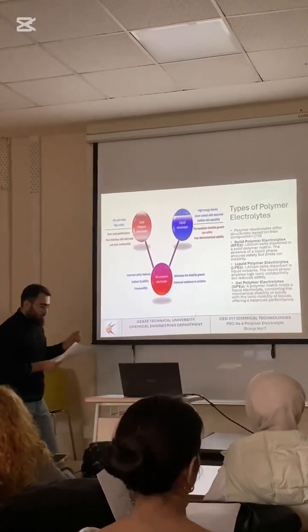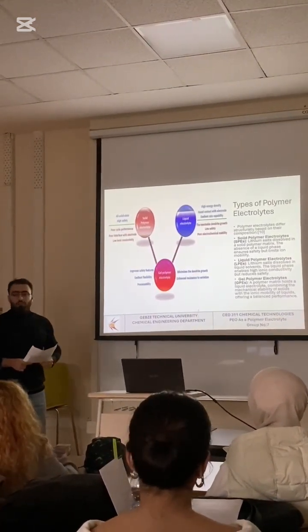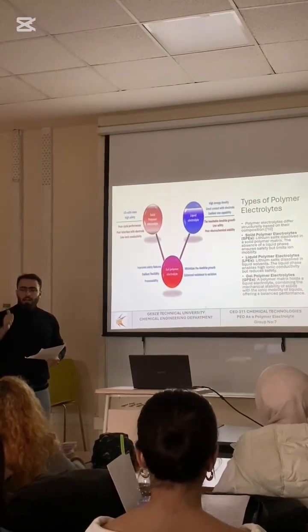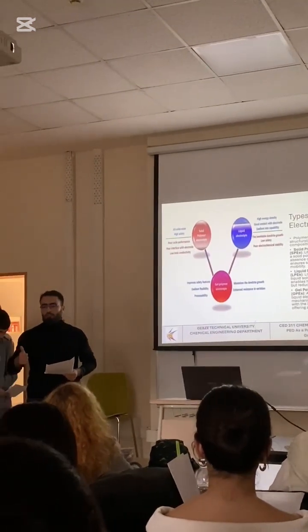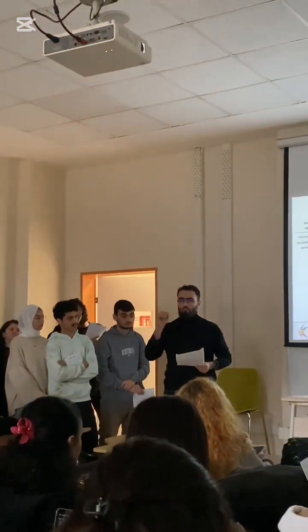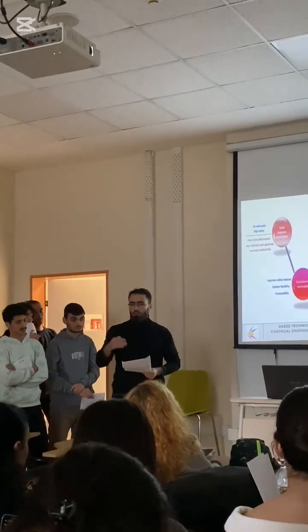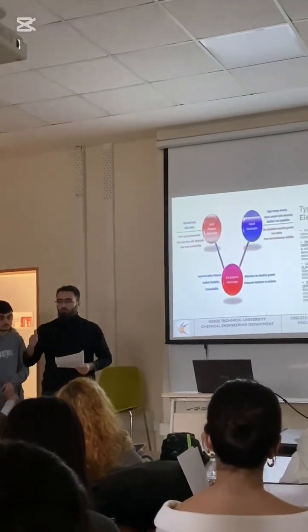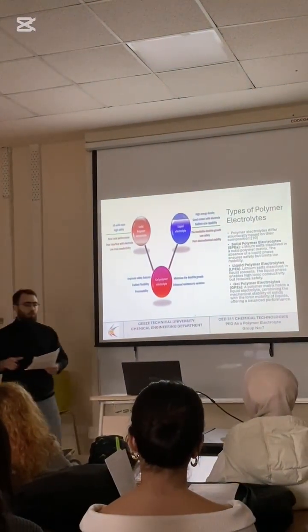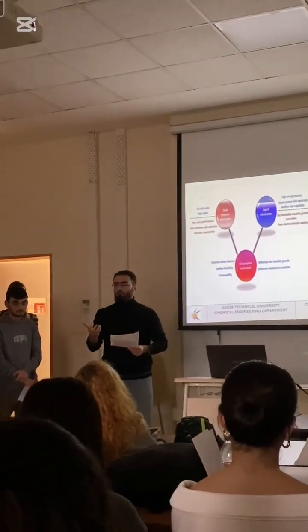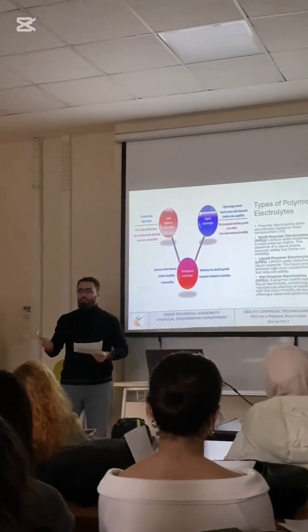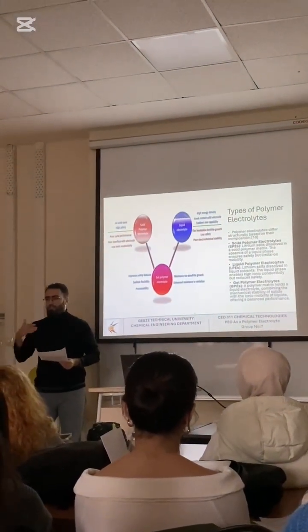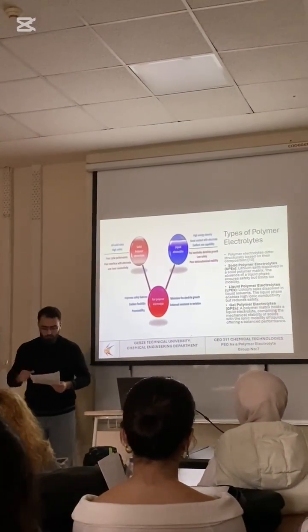So for the solid polymer electrolytes, our polymer acts as a host material and also as a solvent. So in here we don't have any liquid electrolyte, we have just salt inside of the polymer. So our polymer acts as a solvent, so it dissolves the salt, and it is also a medium, a host material for the electrolyte. Because of this property, we don't have any liquid, so we don't have safety issues like flammability.